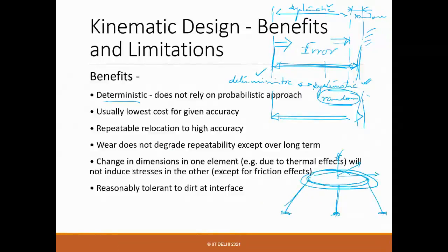But the thing is, it may be tilted, but that tilting you can remove just by adjusting these 3 very precisely. But the moment you have 4, it's very difficult, because the 4th one you try to adjust, you don't know which 3 it is resting on. So you'll start rocking on the other 2. And then you keep adjusting. So it takes a lot of effort.